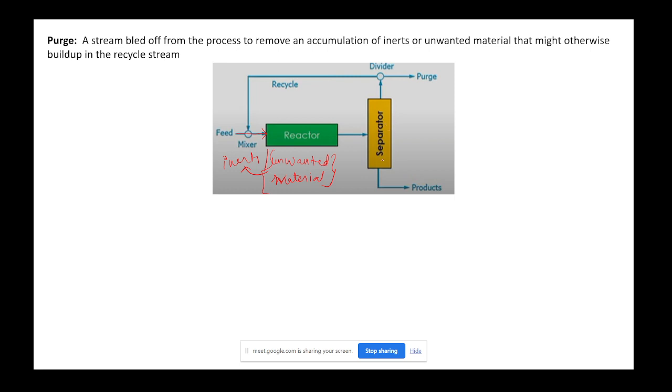Now as I mentioned earlier, to recover the unreacted reactants, we recycle the unused reactants. Since we separate just the product, this will be the phase separator, because it is separated by the difference in states like gas, liquid, or liquid, solid, etc. So unused reactants are sent back to the reactor. Along with them there is inert also, as it is.